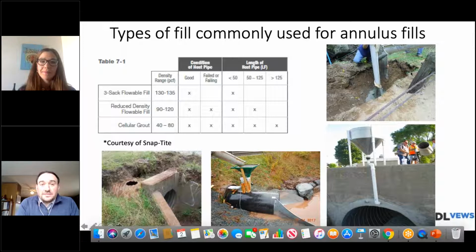That certainly is a buckling resistance, but if you've got a very lightweight pipe versus a heavier pipe, that's all downward force that helps you and aids you in the counterbuoyancy calculation. So if you've got a pipe, for example, that weighs 300 pounds a foot, and then a similar pipe of a different material might only weigh 100 pounds a foot, that is something that you certainly want to consider in those calculations. Yes, you're absolutely correct about that.